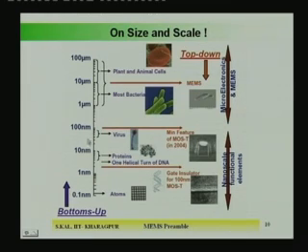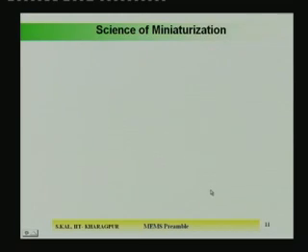comes below 100 nanometer, down to say 1 nanometer, and below 1 nanometer is a different area. So, 100 nanometer to 1 nanometer is the size of the virus, proteins, and the helical turn of the DNA, and this is the minimum feature size of MOS transistor in 2004, you can see here. People are working at 10 nanometer or 15 nanometer level, which is obviously further nanoscale, and this is a 100 nanometer MOS transistor, you can see the gate dielectric is from here to here.